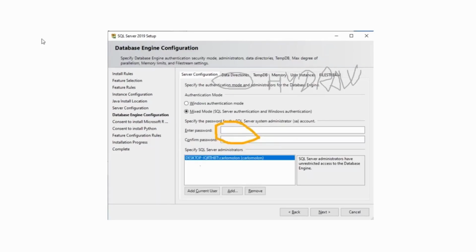And when you do the custom configuration, you already have the possibility to choose mixed mode. In order to connect to the SQL database, HydroCAD requires SQL users in the database. By default, when you install SQL Express with the default settings, it will only get Windows authentication. If you don't have SQL authentication enabled, you will later need to enable it on the machine.